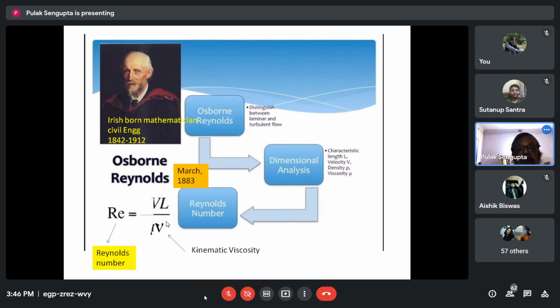So it is not just simple mathematics. What is the physical expression? The viscous force, this is the Newtonian law of viscosity. I will not get into those complicated parts of non-Newtonian law. Newtonian law follows the viscosity equation of Newton, that is the force equals the viscosity and the strain. What does it tell? That is the force or the resistance of a matter against flow. Physically, it means the force that has to be imposed on a substance, on a material, to keep it moving at a constant velocity.